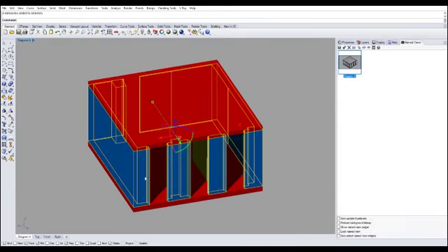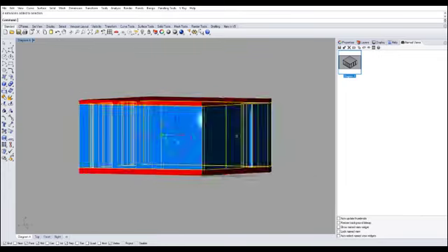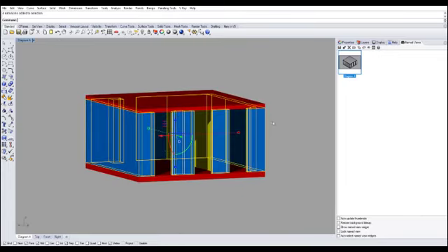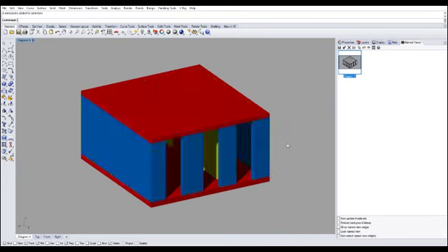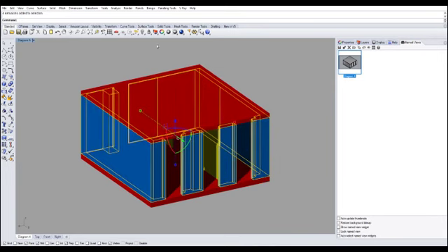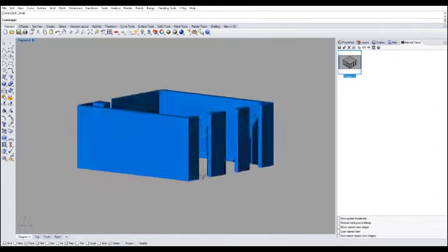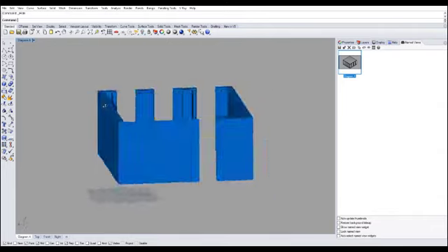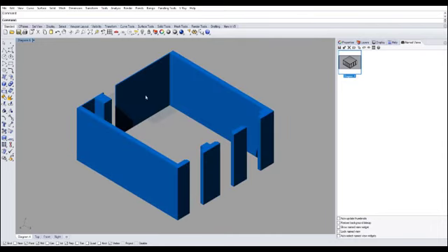So select the walls. Mine's grouped so that we don't have to select all the other components one at a time. Let's just select walls. Same thing, do not click on the hide object, click on the down arrow, select invert selection and hide object. We're not going to render this, we're going to render in diagram A again, a systematic, controlled, consistent view, and then let's render this. My render option has disappeared, so I'm going to go back to V-Ray, render option, and then render.